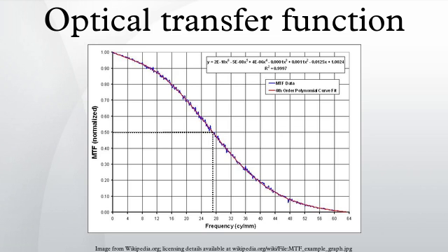As shown in the right-hand figure, an operator defines a box area encompassing the edge of a knife-edge test target image back illuminated by a blackbody. The box area is defined to be approximately 10% of the total frame area. The image pixel data is translated into a two-dimensional array. The amplitude of each line within the array is normalized and averaged.